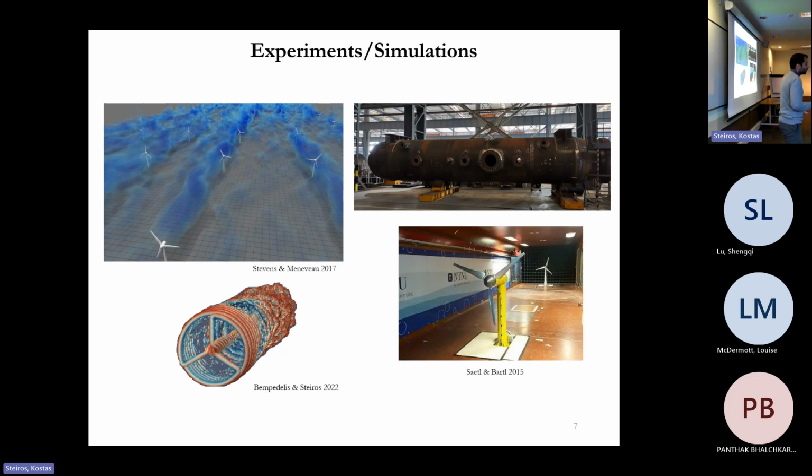Now, the other idea, of course, is that we can start doing experiments, right? This has been, of course, happening for decades now. But again, we have a challenge, especially when we are discussing very large-scale wind turbines, where we have these gigantic sizes and gigantic Reynolds numbers. So the question is, how do we fit this dynamic? How do we squeeze these dynamics inside the lab? Well, because in the lab we have miniature wind turbines, so how do we match the Reynolds number? How do we achieve dynamic similarity?